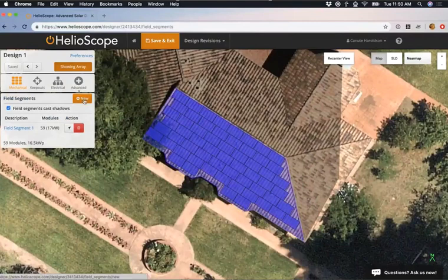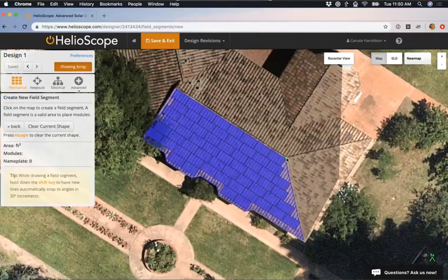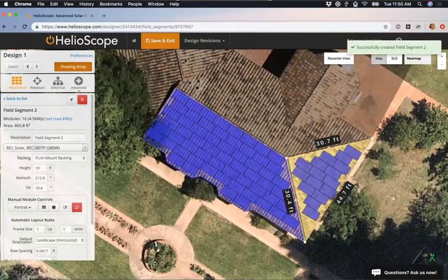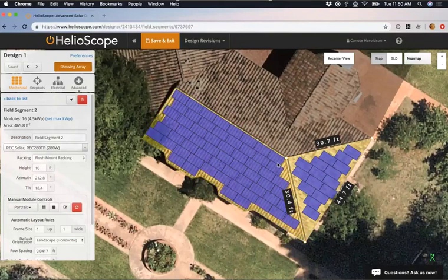So if I click new here, I'm just going to click this left point here, click again, and double click this last point, and that's going to complete the shape, and this copies over all those previous values that I designed. So it's still centered, it's still tiled, it's still got that same roof tilt as well, and that same height. So all I really have to do for this roof edge now is, I don't have a ridge line, so I'm going to have to set the azimuth.